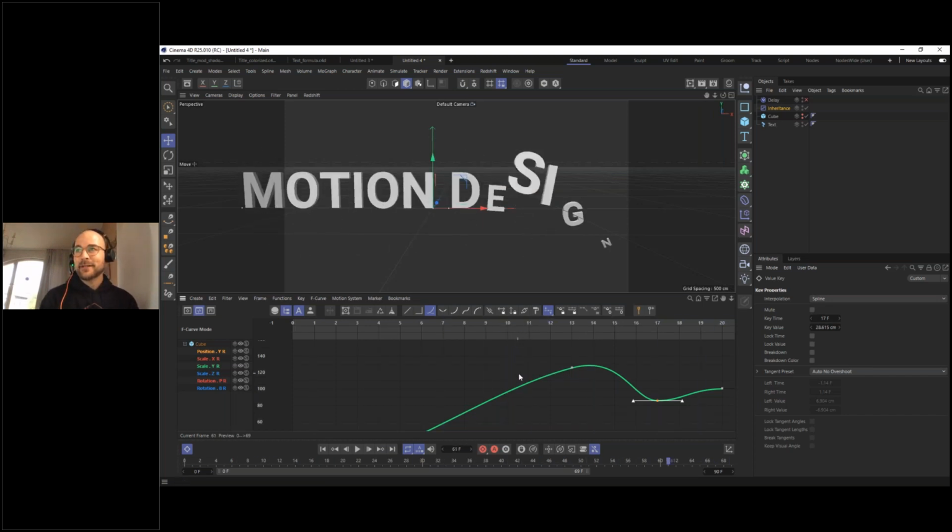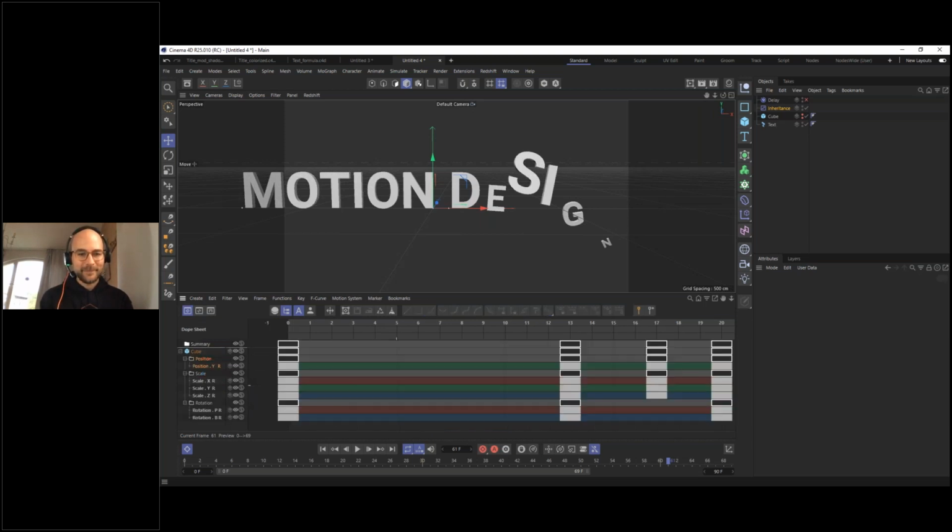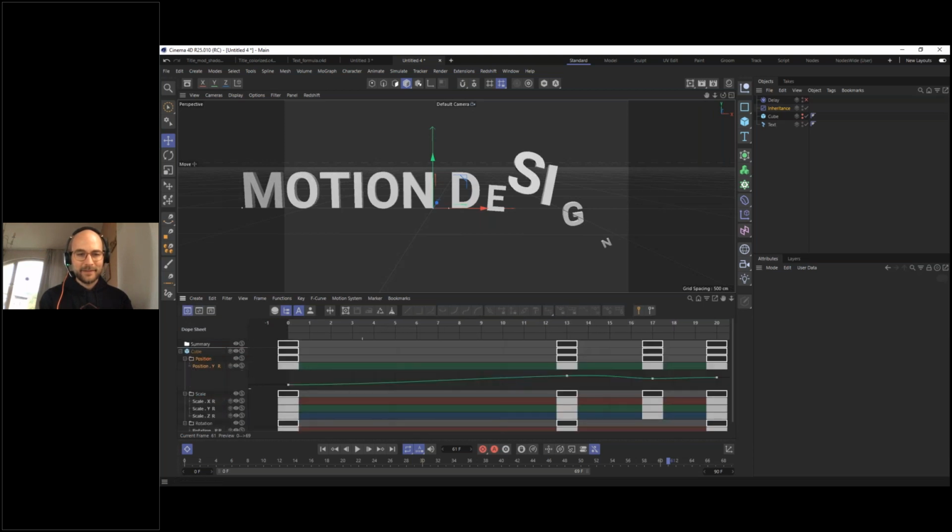Yes? We've got a question here. So Pamela was asking how you got to F-curve mode in the timeline again. How did I switch to F-curve? Yes. Tab, just need to hit Tab. And actually, you have some F-curve here, but I don't like that.